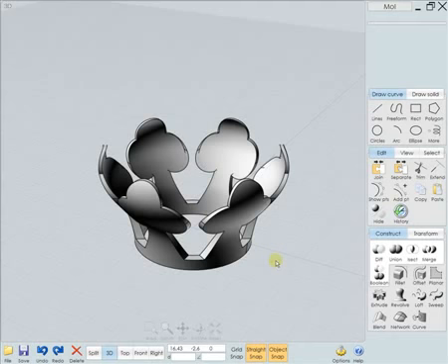Another concept here is it sometimes is helpful to cut pieces out of one common surface. Like if we had tried to model this ring, this bottom ring part, as a completely separate curve than this top part, then it would be really hard to make it as seamless of a connection as this. When it all comes from one common surface and you cut that with different pieces, it's easier for those pieces to join together seamlessly later. And there you go.